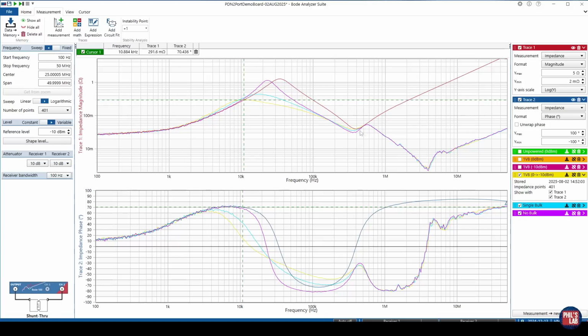We don't go down in impedance after that dip because we don't have that capacitance anymore that provides that low impedance path at these higher frequencies. And therefore we have a far worse impedance profile. Of course, it depends on the situation, but this is why we have decoupling and bypass capacitors, to keep the impedance profile low. And of course, this isn't particularly flat either, even with all of the bypass capacitors and decoupling capacitors in place, but it's better than having no bypass capacitors, as we can see here. So quite a nice effective demonstration, I think.